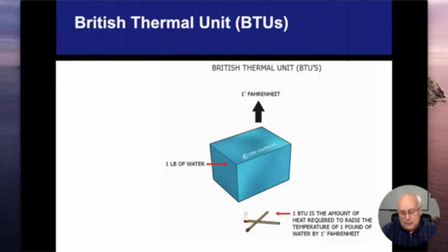And basically it measures in seconds how many times it takes one of those dials to spin around, whether it's half pound, full pound, whatever. And each one, however many seconds it takes to do one full revolution, correlates to how many BTUs are being used of natural gas.